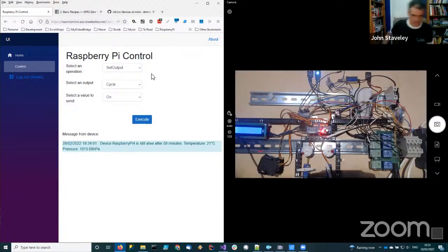So what's happening here? This is my Blazor application. When this is instantiated, it creates a persistent connection into my data center and the IoT hub. When I click this button, a SignalR message from my browser is sent up to the Blazor application in my data center, which then sends a message to the IoT hub, which my Raspberry Pi is subscribing to updates from.